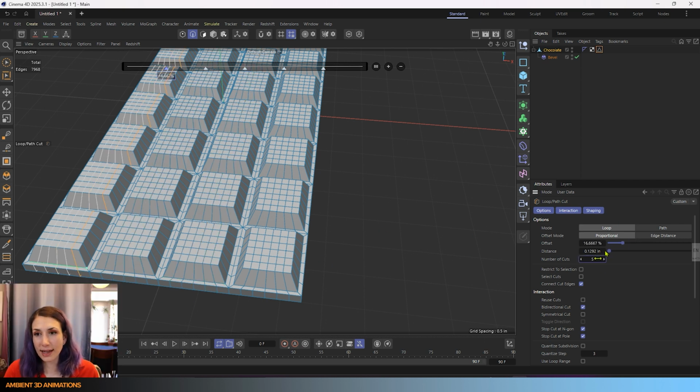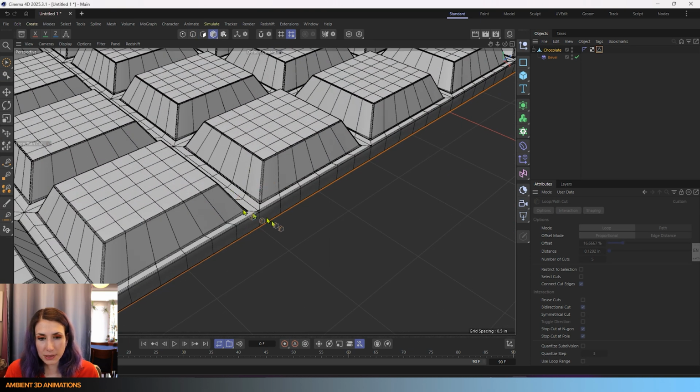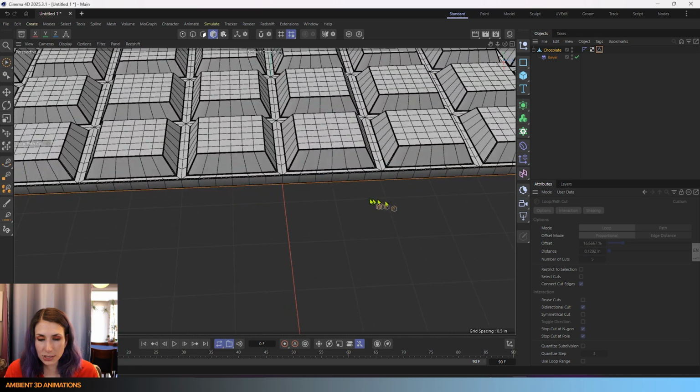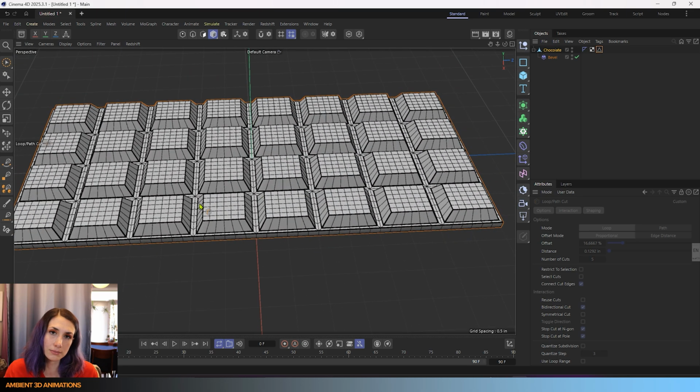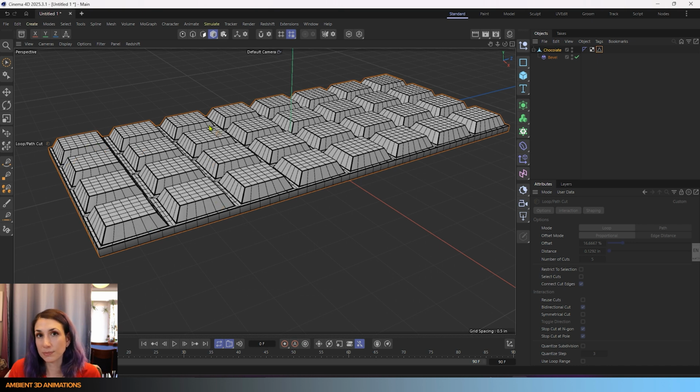And since we made that selection earlier, if I go back into model mode, you'll see that the only edges being beveled are the ones we had selected with our selection here. So regardless of how many more edges you add, it'll have that memory of which ones we're beveling. That's just useful to keep in mind for anything you're 3D modeling.